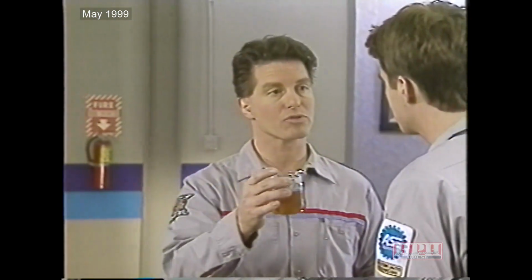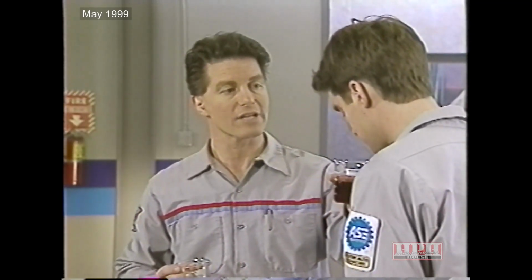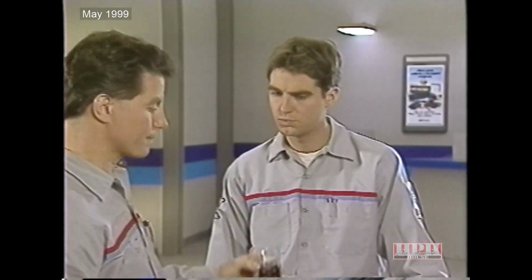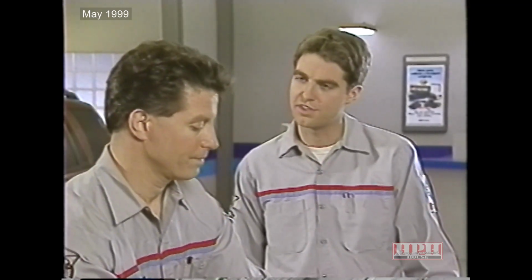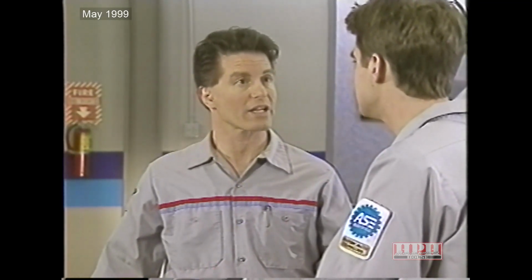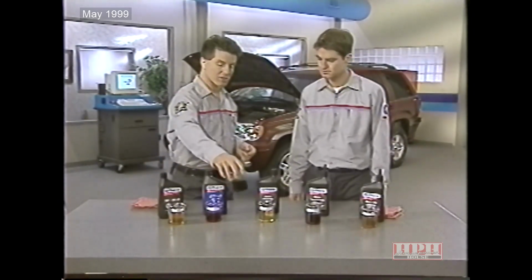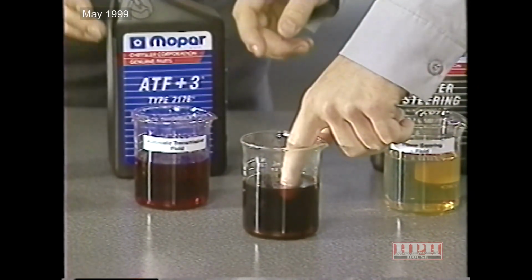Engine oil has almost no odor, while automatic transmission fluid has a slight odor. Well, what if I have a cold and I can't smell a thing? Well, that wouldn't be a problem. Another way to identify the leaking fluid is to check the viscosity. Compare this sample of the fluid that is leaked out to this new automatic transmission fluid.